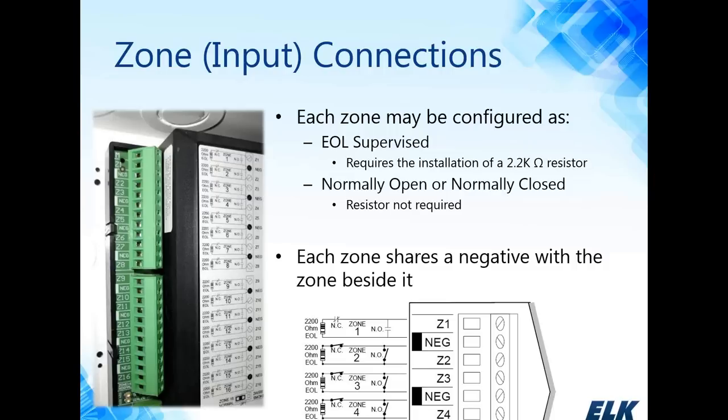If you're thinking of putting the resistor inside the enclosure, then I would suggest just making the zone normally closed and not using the resistor, because you lose your supervision on the zone.